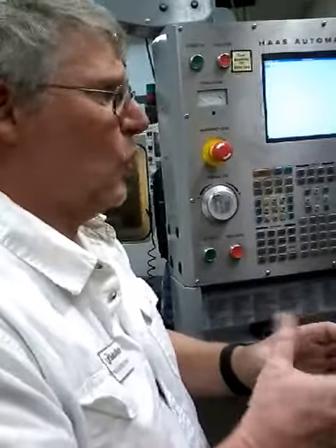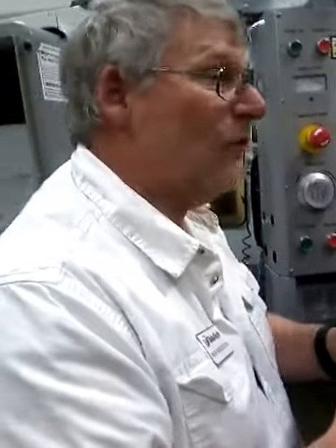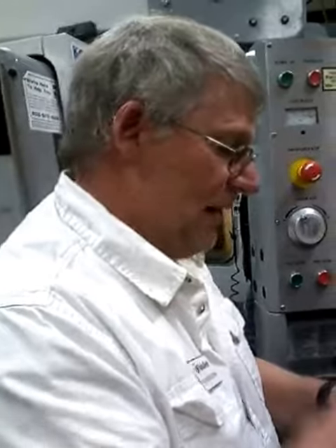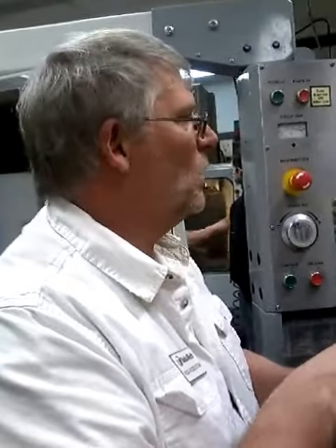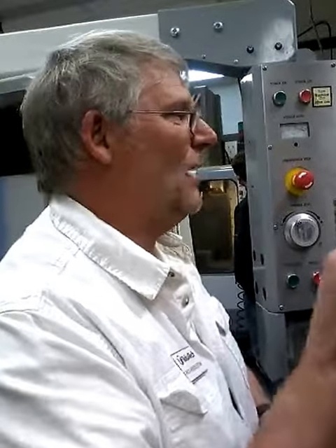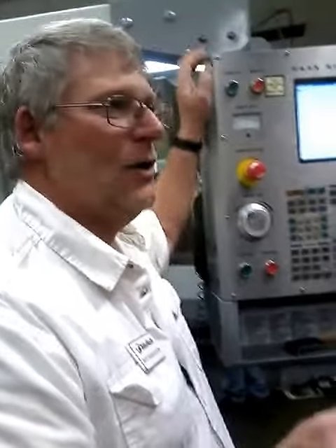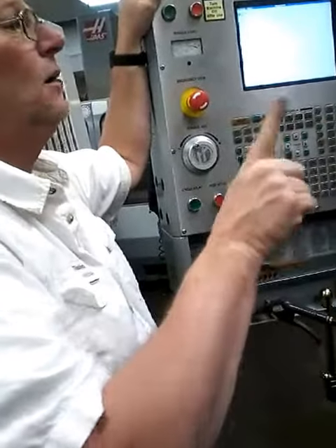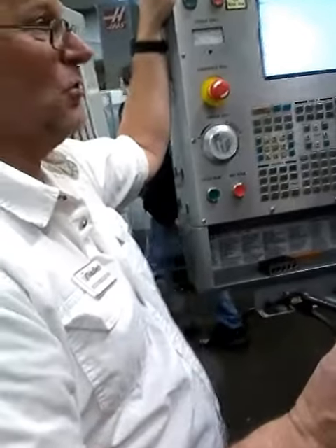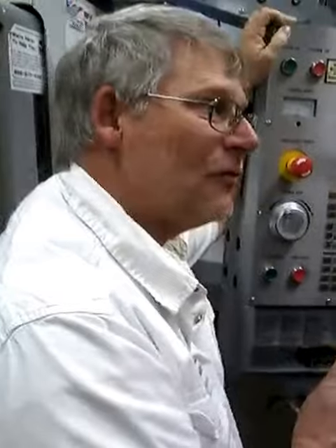It's actually sawed really crooked, but it's about 4x4. I want to send my tool to the center of the block. Where would that be in X and Y? 2 and 2. X plus 2, Y plus 2, from the bottom left corner.